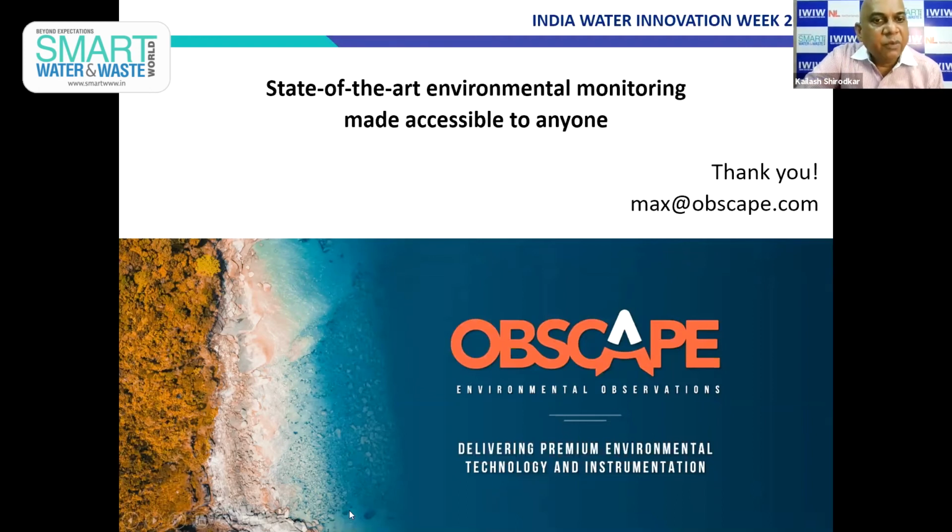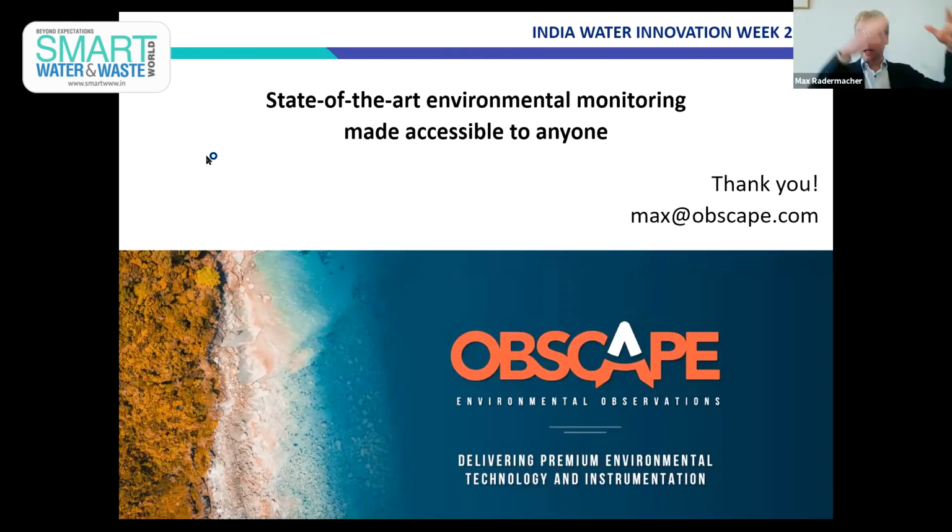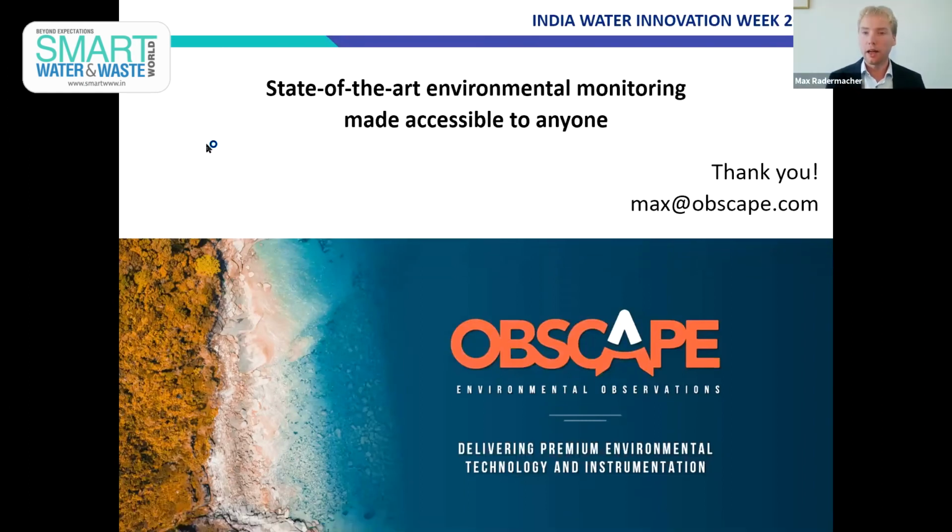Thanks, Max. We have one or two questions for you. One of the questions is, can you briefly explain the functioning of the wave buoy, please? Yes, the wave buoy is based on motion sensors, mainly an acceleration sensor, so the buoy moves up and down with the waves, and by recording the motion of the buoy, we can derive all the relevant wave parameters as well as the directional wave spectrum.